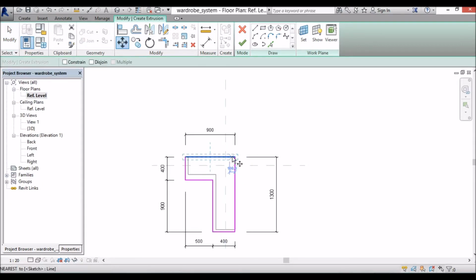Then I can select the line really anywhere, and it hasn't grabbed onto it. Okay, I'm holding down my left mouse key and pulling it down. Now it says 100, I only want to move it by 50, so I just type in 50 and click to accept.